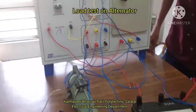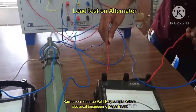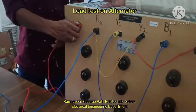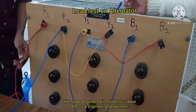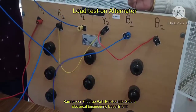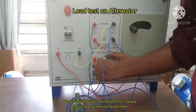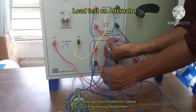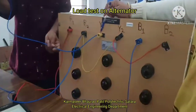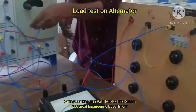Now what was left was the ammeter's connection. From the R phase we are connected to the ammeter common, and the second terminal, the 5 ampere range we are using, will be connected to R1. Y1 will be connected to Y, B1 will be connected to B. So the stator output Y gets connected to Y1 of the load and B gets connected to B1 of the load.